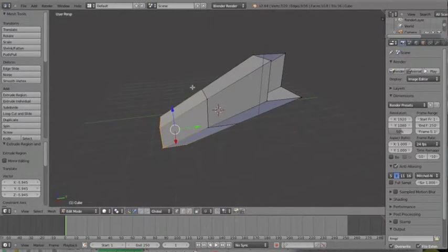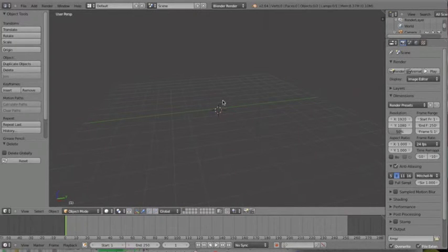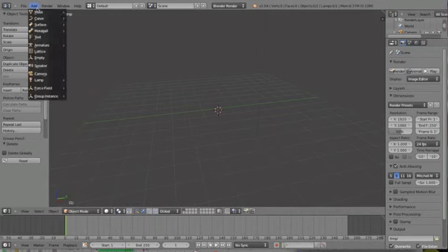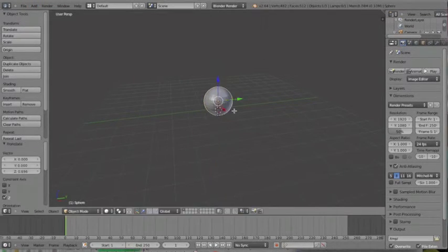The last thing you need to know is that the cube is not the only mesh you can use, so I'm going to delete this weird thing by pressing X or Delete and then scroll over to the Add in the mini bar at the top. You may also access this menu by using Ctrl A to add a new mesh. For this tutorial I will use the UV sphere. Now that we have our chunky ball, we can select a bit of it, other than all of it.